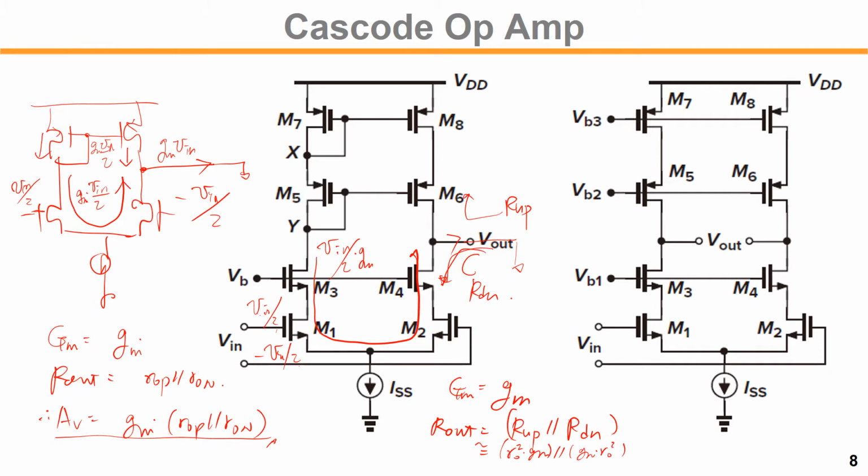So by having the cascode, you will get higher gain. For the differential amplifier with differential input and output, you can use it without the load current mirror connection.